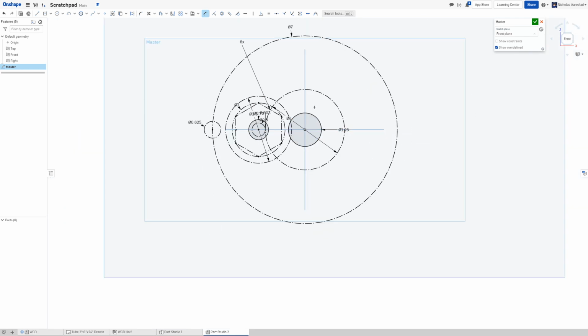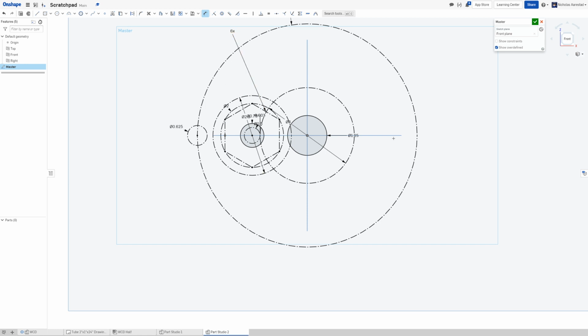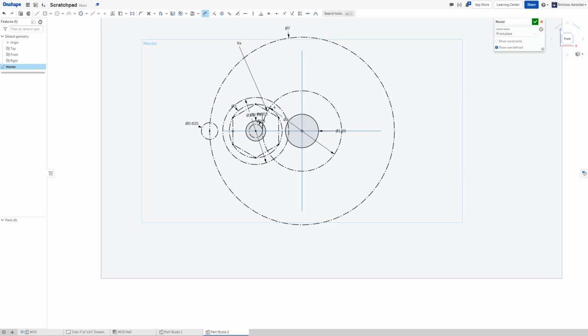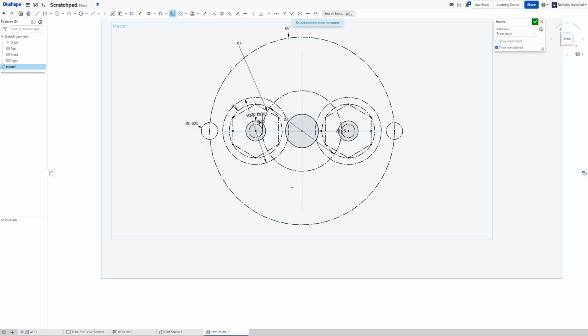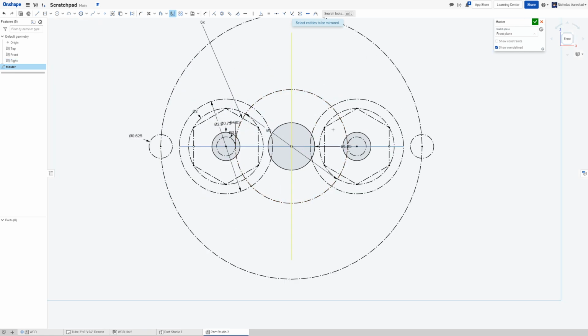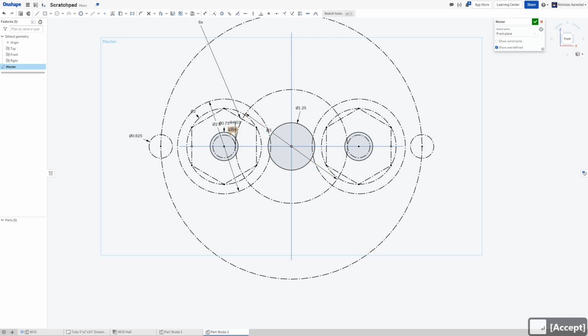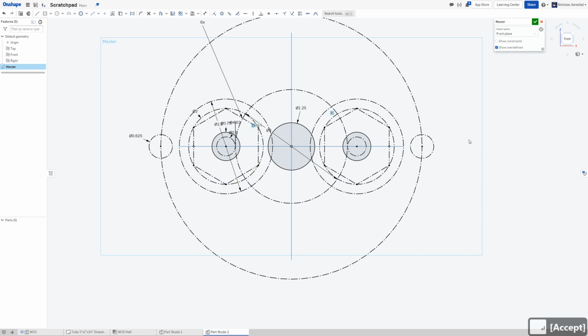So that's, other than the mirror that I'm about to do, almost the entire construction geometry that I would use for this. So for mirror, click the mirror button, select that plane, and we can drag over all this to mirror those. And then the nice thing is, down the line, say I wanted this to be 12 instead, right? You can see it affects both of them, which makes life much easier.